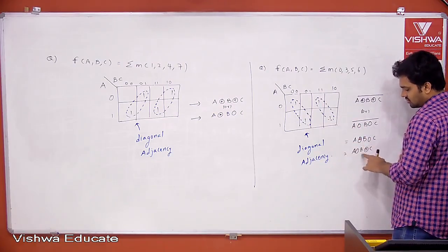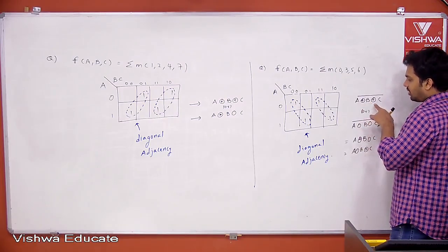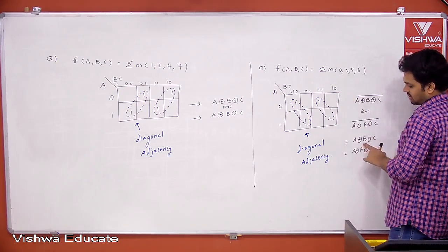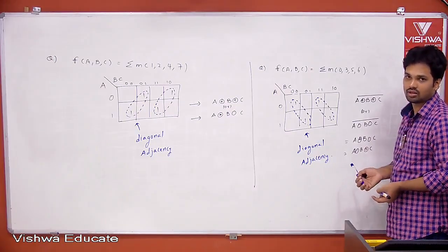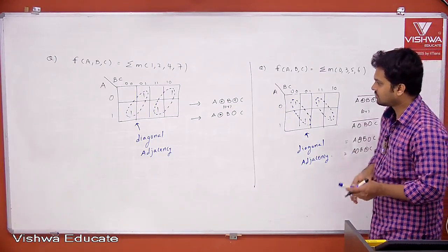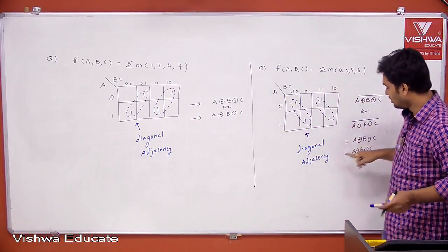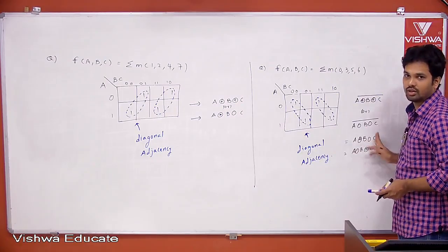Your answer will satisfy both of them. Both are valid answers. So it is the complement of XOR or XNOR; either this or this is the answer. So if it is satisfying an odd number of ones or an even number of zeros, XOR or XNOR. Otherwise, it is a combination of XOR and XNOR. Okay. Copy it.